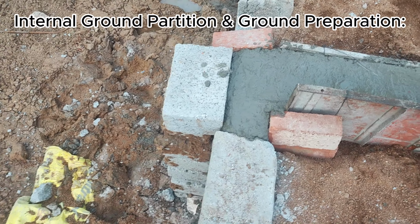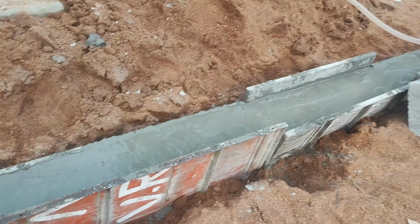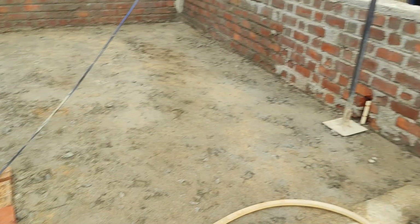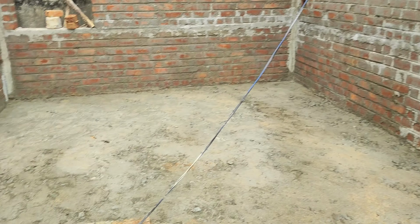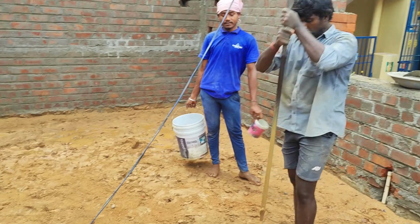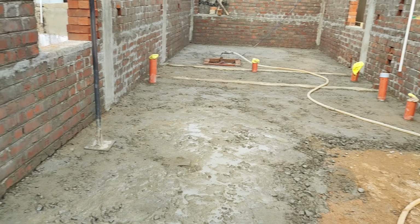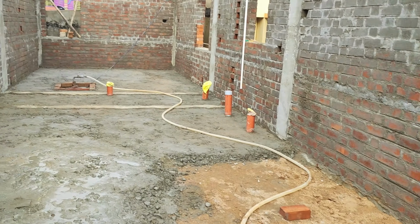Internal ground partition and ground preparation. With the outer structure in place, internal wall partitions are built to define rooms and corridors at ground level. The ground inside is carefully leveled and compacted for flooring. Before laying concrete, an insecticide chemical treatment is applied to kill and prevent termites or underground pests. A concrete mix is then poured to form a smooth and solid base floor.